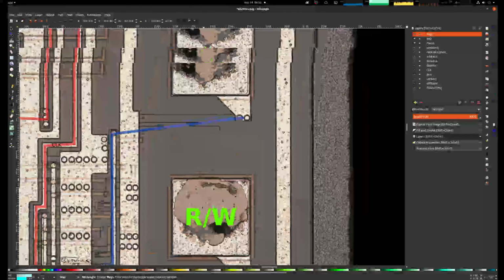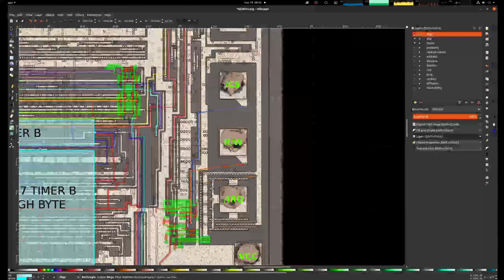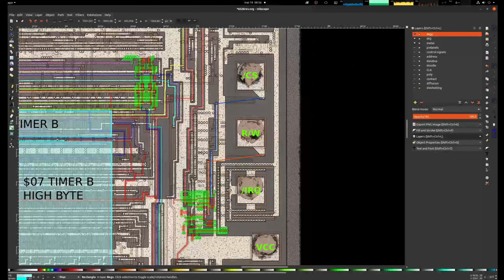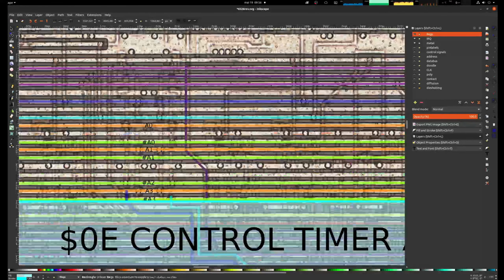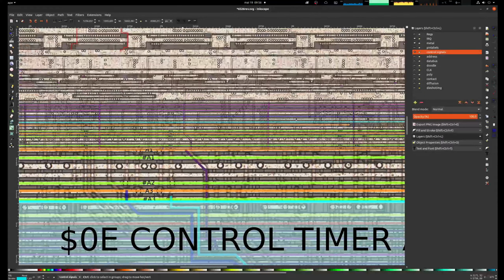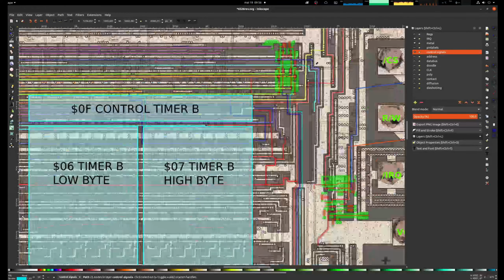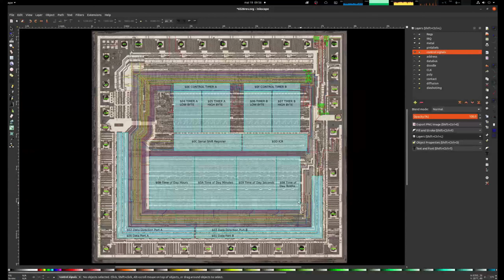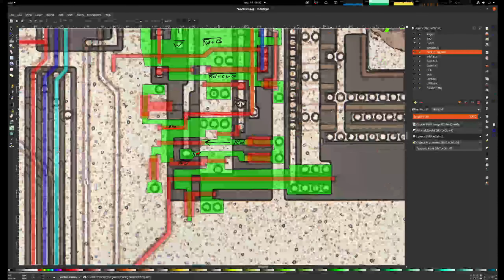And I think we should look a little bit at the control signals, chip select and read write, because they are very important for this chip. As you saw when I decoded the address decoders, we always have address, and we also have control lines for read and write, and those read and write lines go all over the chip. So you can't just have a small transistor, you need amplification for that. The reason why I say amplification: you can't just take a signal and drive a large transistor. You have to amplify it in several stages often. Or that's what I see.